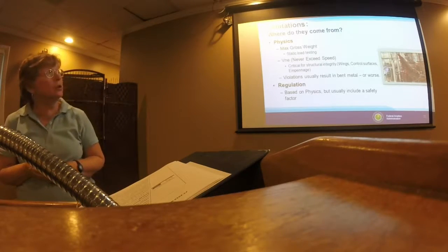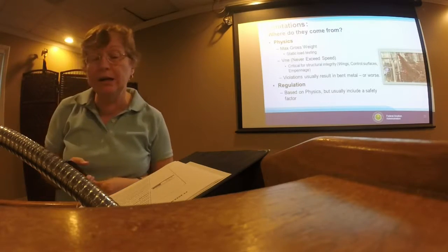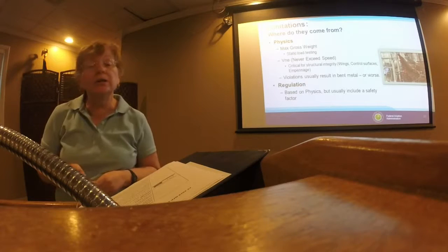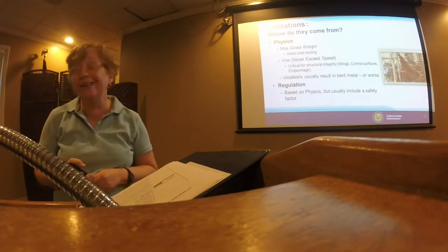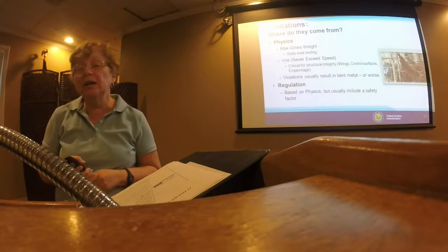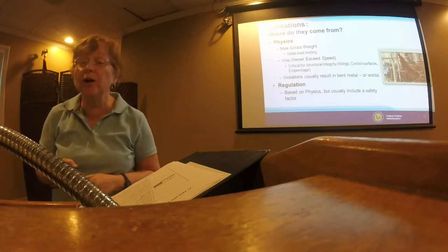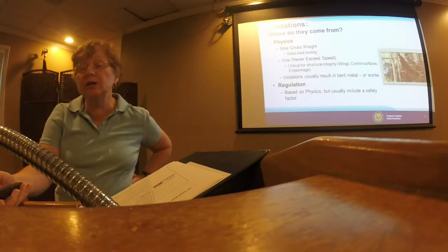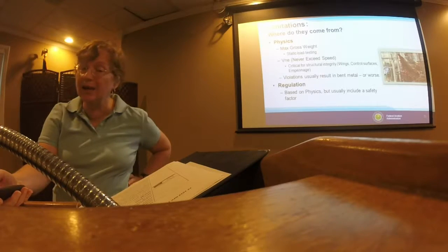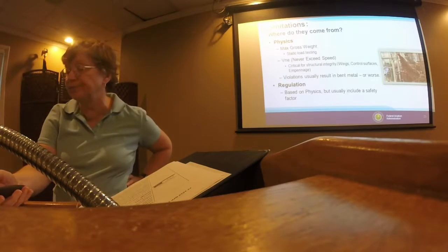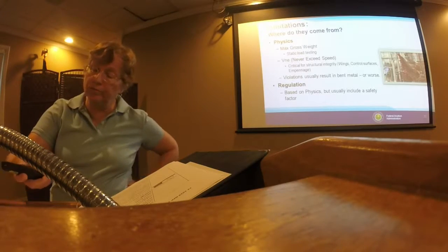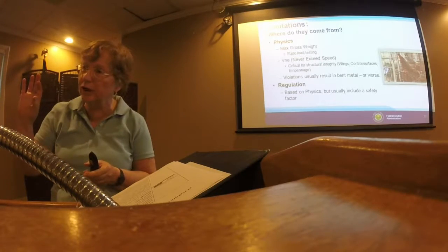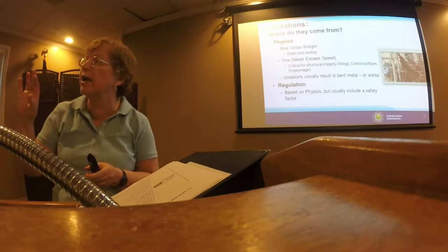VNE is also determined according to when the onset of control flutter is experienced. If you violate these limitations, then you are going to have bent metal. Regulatory limitations are based on physics, but they also include a safety factor. So the airplane is as strong as it is, but there's a little fudge factor for when Mother Nature adds to the stress.